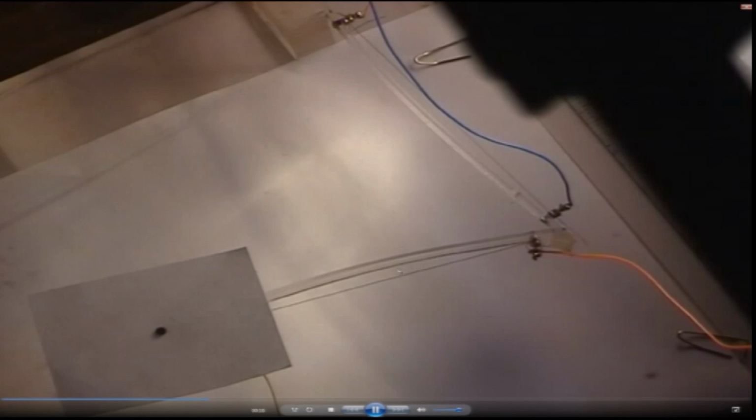If I just show you, you can see that in this case there are two links in which we have these SMA wires in offset, and as I am increasing the temperature, the SMA wire is getting shortened, and that blocked force is actually bending these links, and as a result this tip point which we are tracking, in fact you can track it and you can create many different trajectories as a simple two link flexible manipulator system.